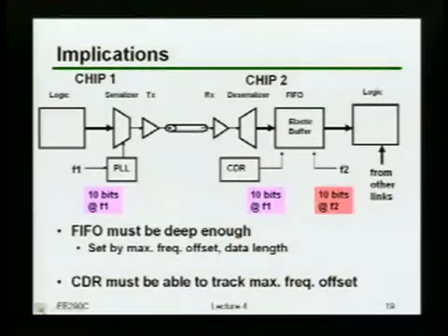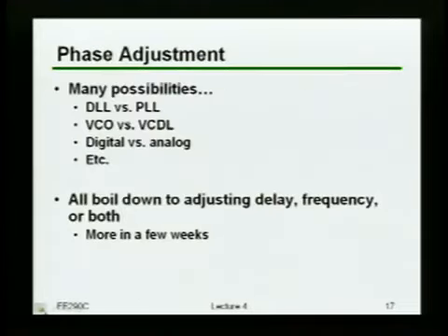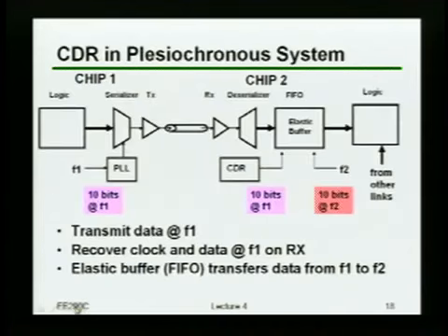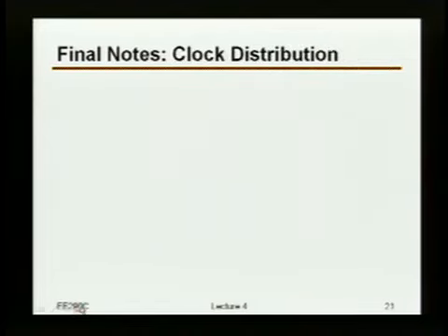But basically, a quick reminder for everybody. We talked about having clock and data recovery systems and why that was advantageous from the standpoint of eliminating deterministic errors, as well as allowing you to have different crystals on different boards. We then also talked about the implications of that in terms of how you have to have buffers in order to deal with the frequency offsets. And then we made a note about the difference between a serial link and a parallel link.